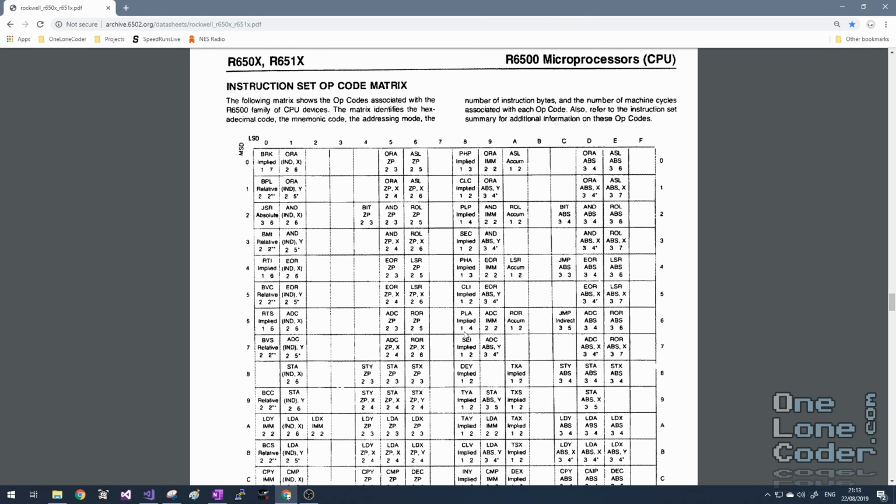Those little programs need time and a clock in order to operate. But why is that relevant to these illegal opcodes? Well, a CPU in reality is not like a big switch case statement in C or C++. It doesn't know that the bits it's seeing for its program byte are invalid. It uses those bits to configure its internal arrangement and start its little internal program, its microcode program. And so these illegal opcodes will do things, but they'll do interesting and unexpected things.